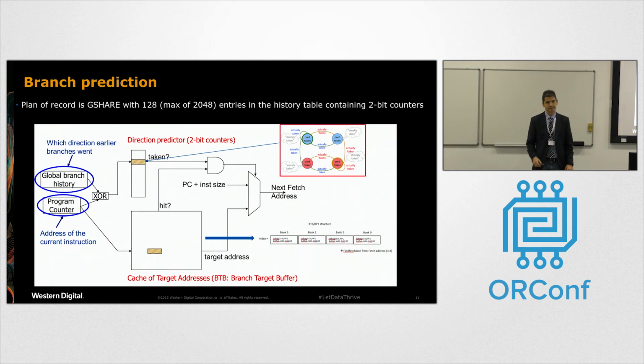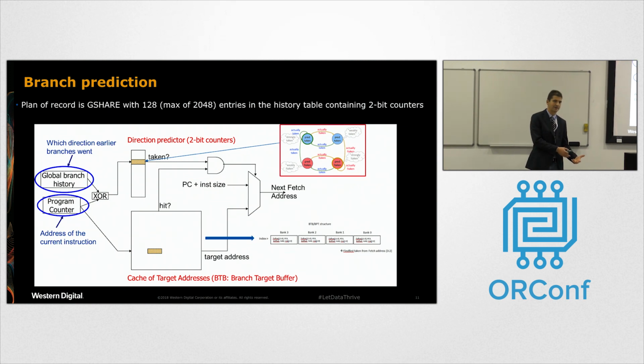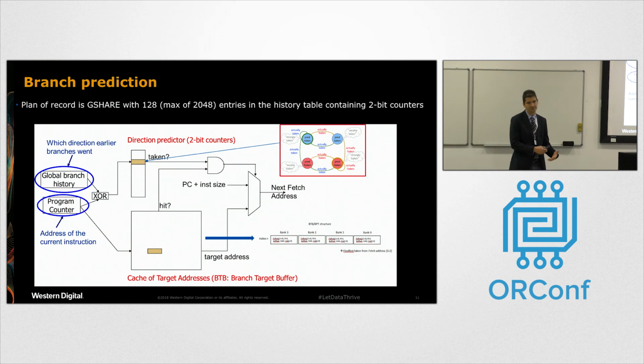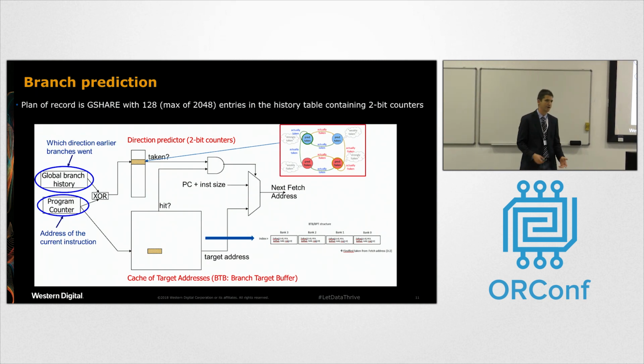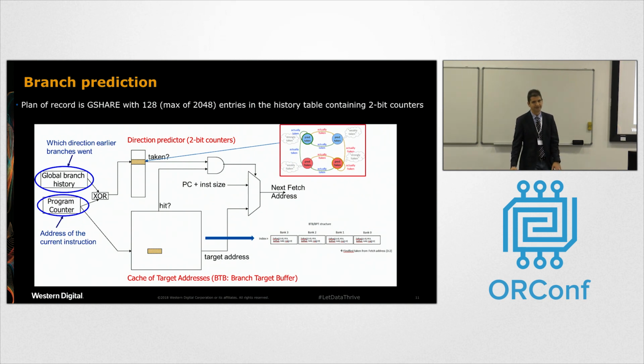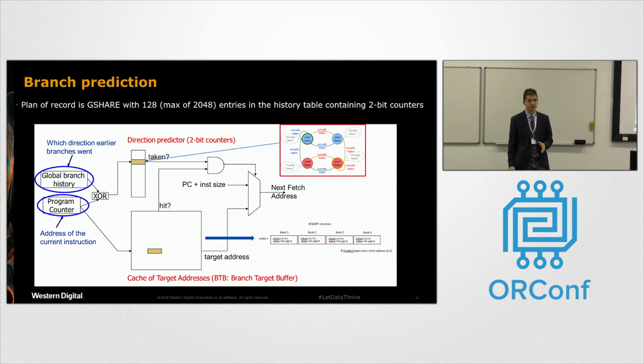One of the things that is very important for the performance is obviously how you do the branch prediction. So in the embedded design, from the computer architecture classes, we learn BTB. You also learn G-share, and maybe at the end there'll be some fancier scheme using DEC Alpha, like a tournament predictor, etc. In embedded projects, you will kind of stop at G-share.